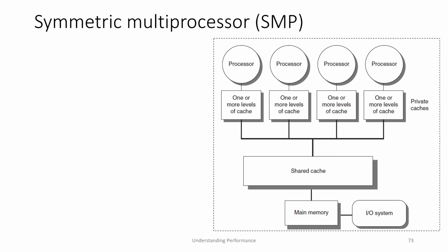In the same lines, when we are talking about caches, typically if we have a single application running on a single core, the cache behavior is predominantly understood by using three types of misses. One is cold, other is conflict, and third is capacity. Cold misses are those which will occur whenever we are trying to access a data item which was not accessed before.